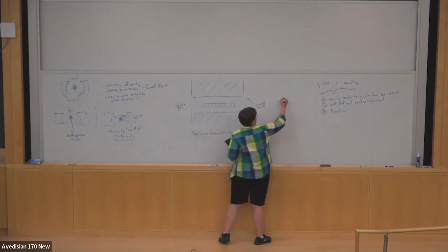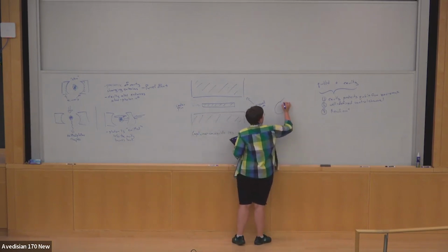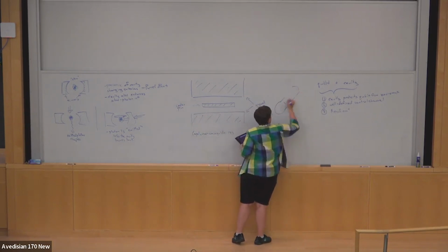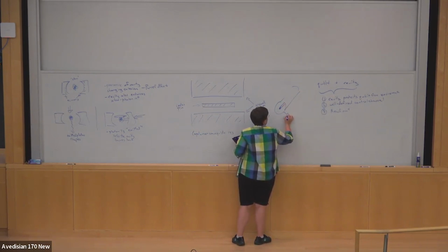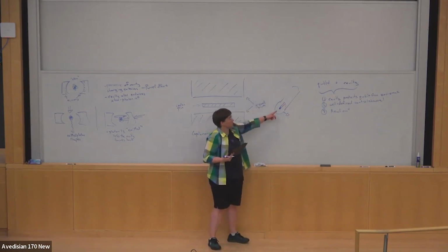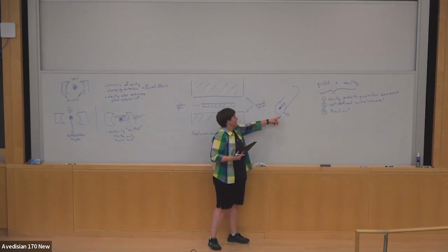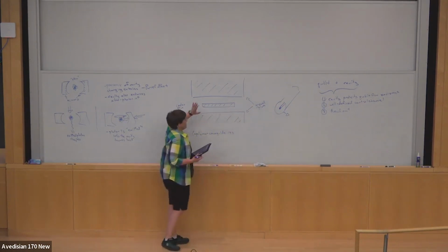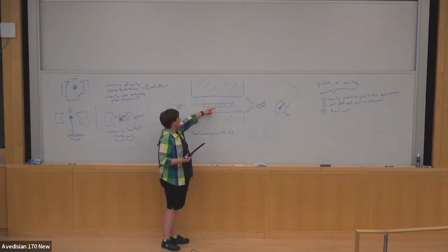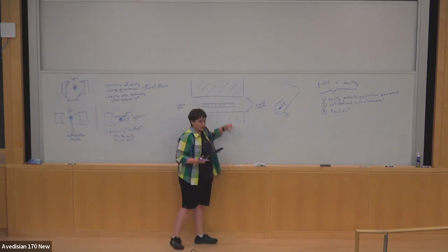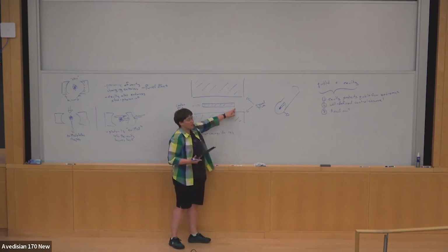For me, I find that the most intuitive way to imagine coplanar waveguide is to go back to E&M and think about a coax cable, right? So you have a central conductor on which voltage propagates, and then you have a ground plane on the outside. And so this is the pancaked 2D version of that. You have a central conductor and ground plane on either side, and it guides electromagnetic field modes along it until you get to the end of the center pin, and then they bounce back.